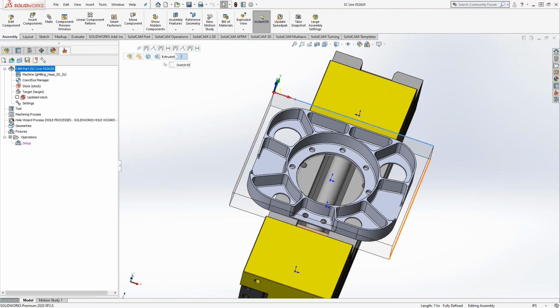So like I said, I would put that coordinate system in the center, and then using the probing software, I would find that center position, because that way, if I have a little bit extra material down here and smaller over here, the probe is going to automatically put that right in the center of our stock. So if we're a little bit out of sync, that way it kind of corrects everything. Does that make sense?